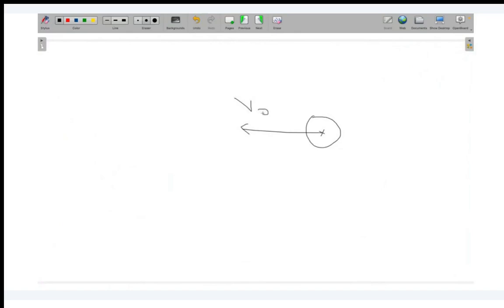At location P, along your x, y coordinates this is in the positive direction because the velocity here is in this way, but according to your radial coordinates it is coming radially inwards, so it must be negative. If it was in xy coordinates, it would be positive. But since it is in radial and theta polar coordinates, we take it as negative.